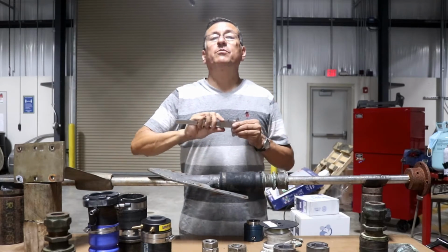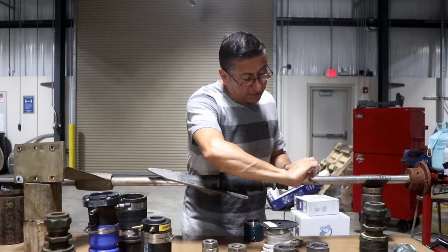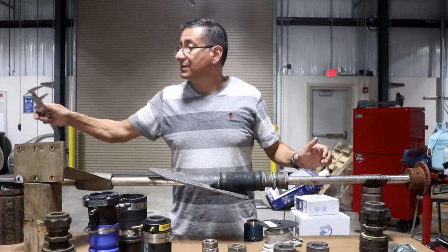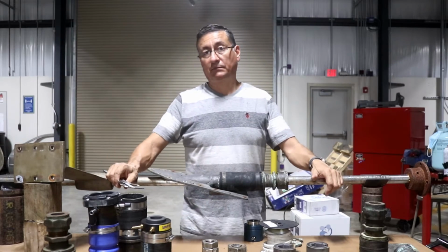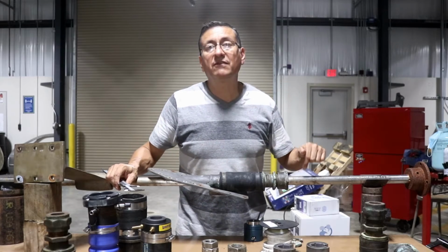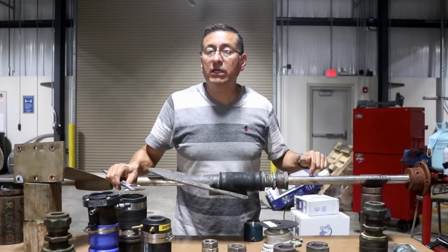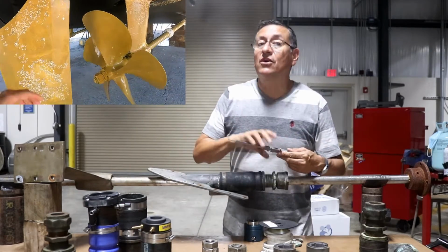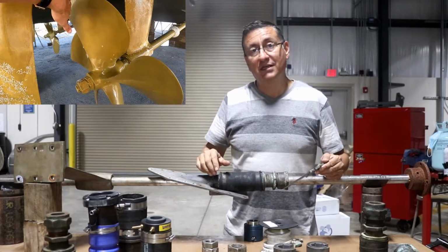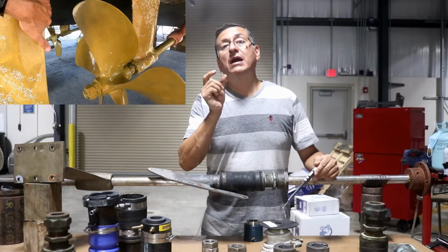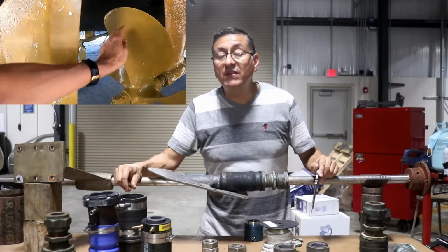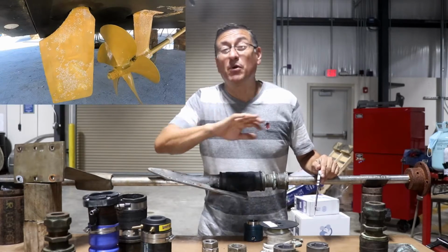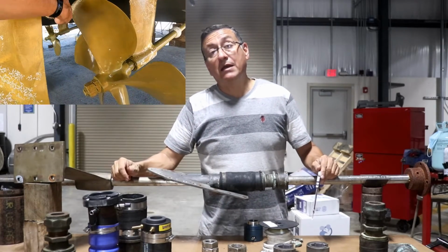The micrometer is an important tool. You need to verify the diameter of the shaft in order to replace it with another one of exactly the same dimension, the same length, and the same diameter. My friends, what happens if you receive a shaft a little longer than the original? Right now, the distance between the rudder and the propeller is short. And you remember previously I explained what happens if that distance is less than 15% of the diameter of the propeller. Probably when you move the wheel, the boat responds dramatically. Alright? Be careful with that.